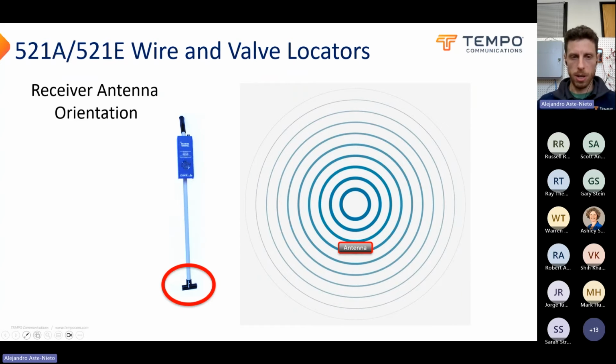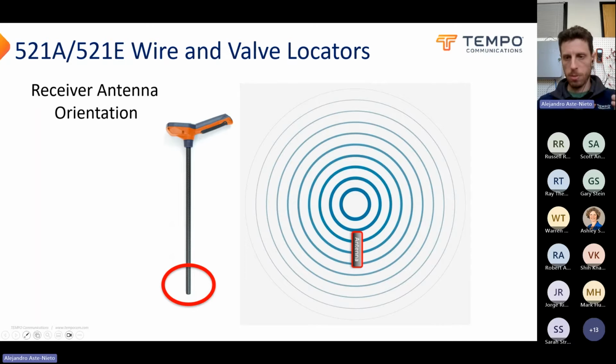That's why on our 501 locator, we have this little cylindrical antenna perpendicular at the end there. It's going to catch the most of that wind right over the wire. So if we rotate the wind tunnel more and more towards the eye, it's going to get less and less wind blowing through it until it doesn't catch anything. It's just going past the wind tunnel, no matter the wind speed. So that's why you get a null when you're pointing at a wire. The orientation of the antenna is such that it's not listening for anything moving in that kind of way.